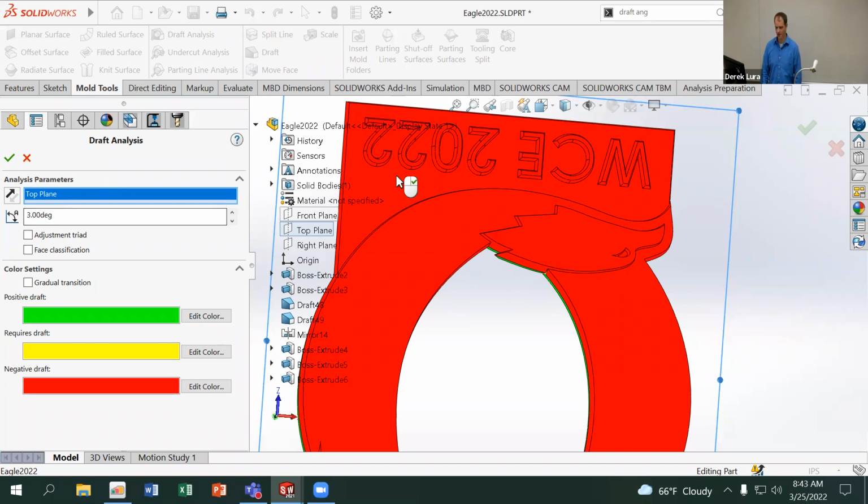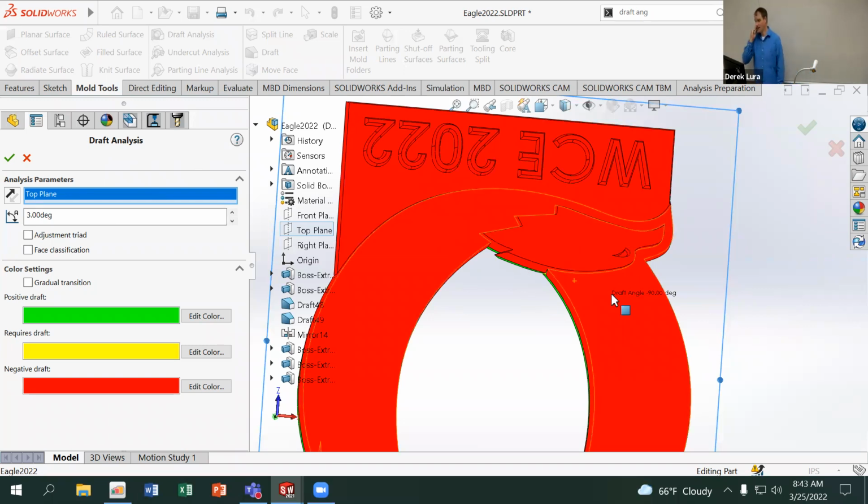It's also going to be a little bit harder to get those kind of smooth edges. This is not the best mold design because I have hard edges around this entire part. If I really wanted to optimize this for even better performance, I'd take all those top edges and round them all, right? Which I could do just by using this very small round on the entire surface.